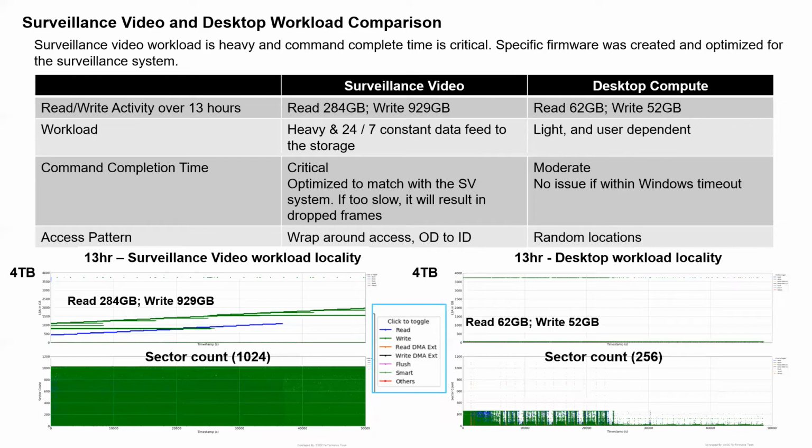Also, if you look very closely throughout that lower graph, you will see some dotted vertical lines that are orange in color. Those are read DMA commands. Those are kind of unique to compute functions. You'll never see one of those in a video transfer.